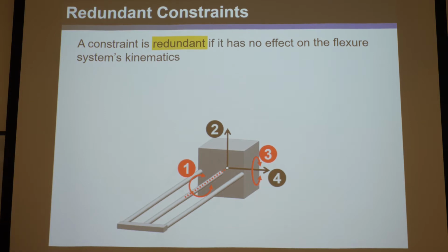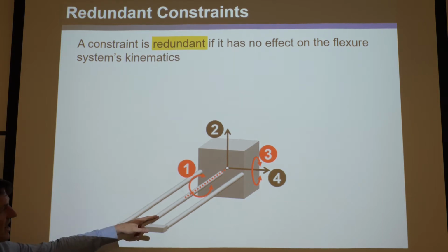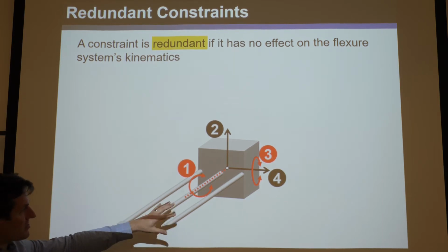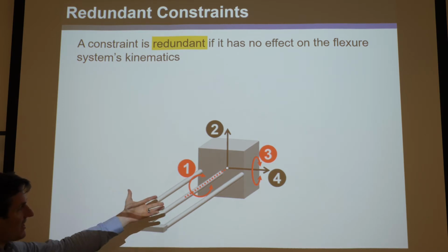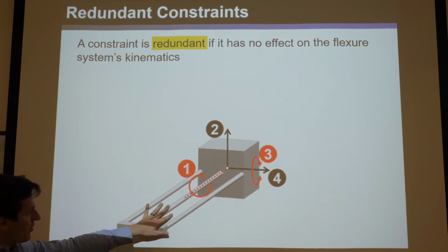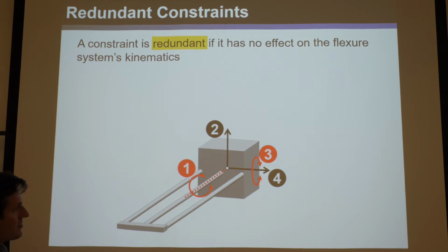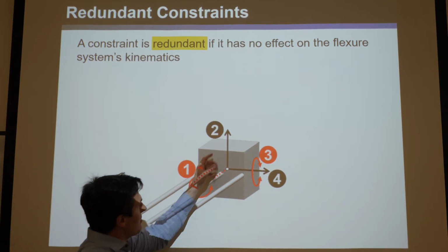Say it was possible to get an absolute clone of a grad student, and they did the exact same job. One is redundant, right? So this constraint is not doing anything different than these constraints. It's still killing the same 2 degrees of freedom. All 3 of them are working together to kill just those same 2 degrees of freedom. The translation here and the rotation here.